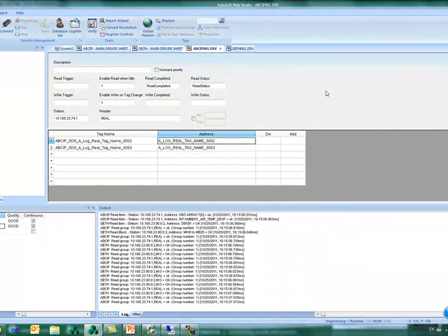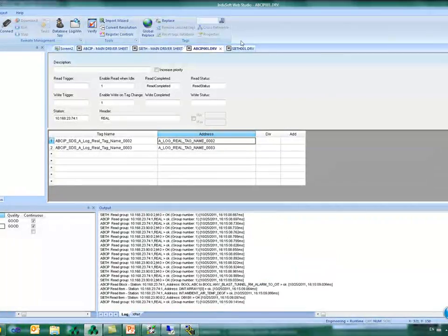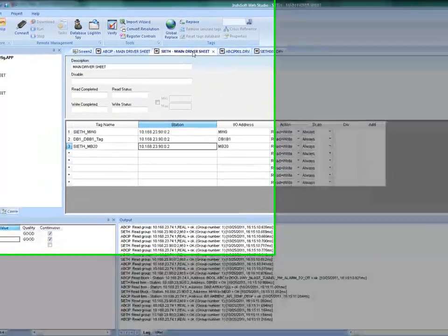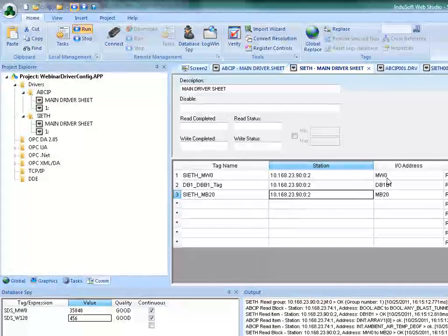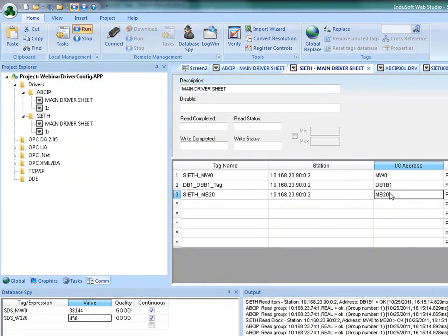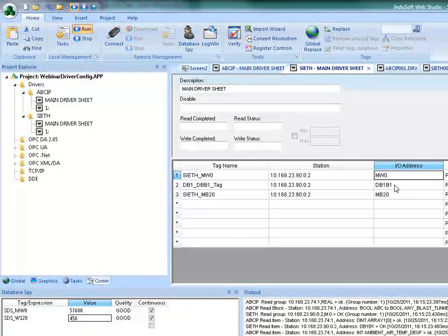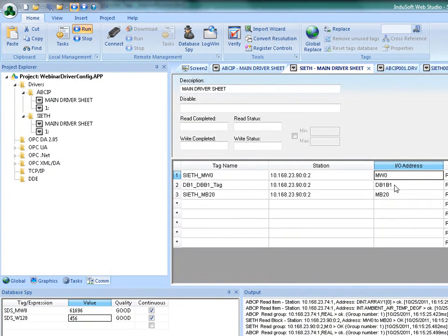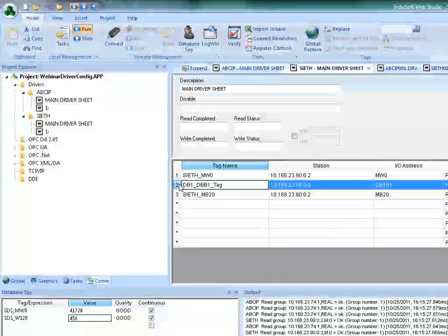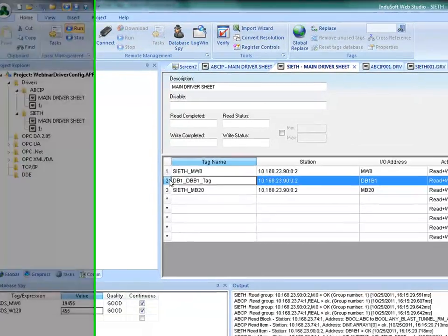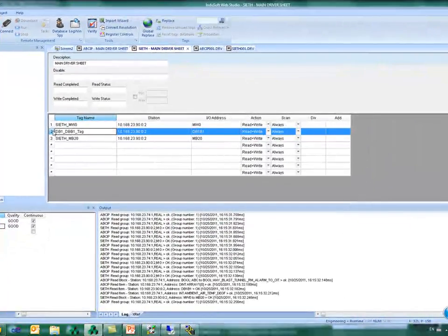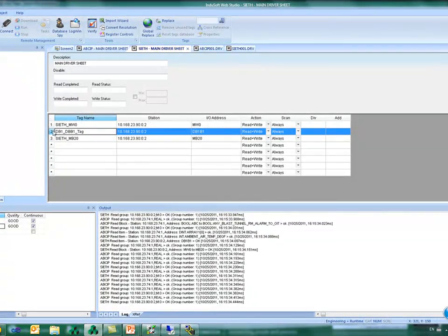And when you're using a PLC that is based on memory, like the Siemens PLC or Omron PLC, then you should use the memories pretty close to each other. So program the PLC thinking about the HMI as well, at least on the communication part. Communicate with as few DBs as possible to the Siemens, and you're gonna have a real good communication. Okay?